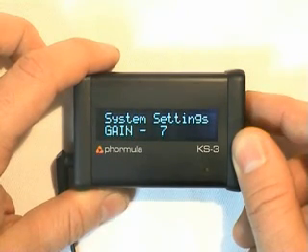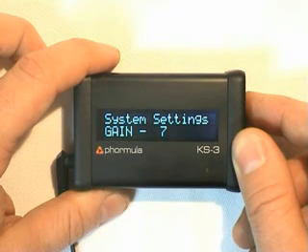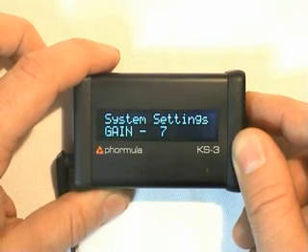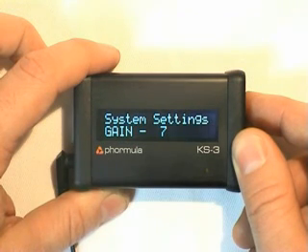And one other point to note is that the signal cable should be routed away from sources of interference. So don't go zip tying it to your HT leads, because you won't get a particularly good clean signal back to the device.